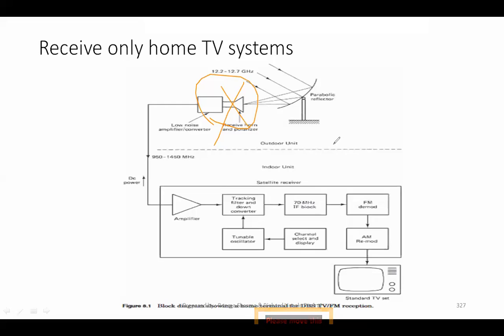So they make it more robust, because there is a lot of rain, a lot of dust, as you suggested, and a lot of sunlight. It needs to go through all this harsh environment, right? So max, probably about 5 years is the life of this polarizer, the receiving horn. So this full thing will be replaced actually.